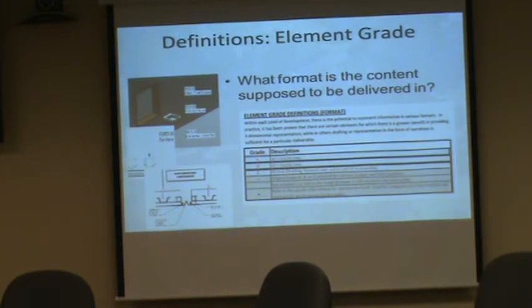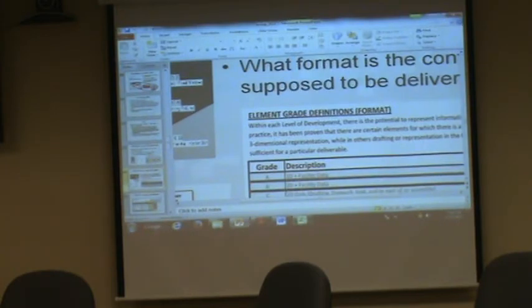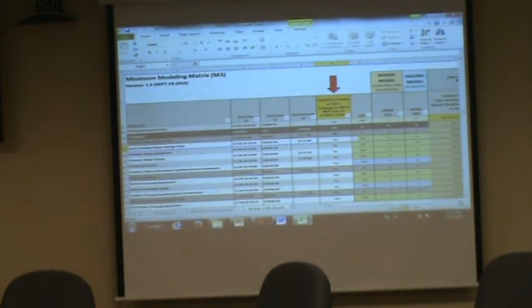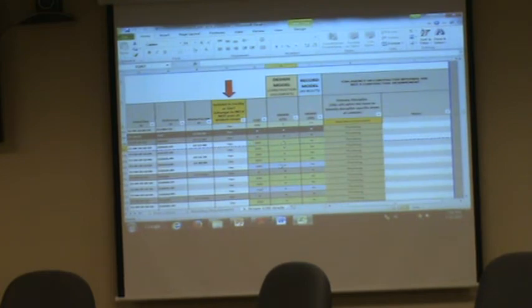So we go back over here to the N3. We'll say, for example, I need grade A for construction documents, but I need more when I do the record model. So it's telling you, depending on what your contract says, to get out drawings, I need this, but when I deliver an as-built model or a record model, I need this. So it's dividing up the information and the model? Yes. Two separate? Two separate things.